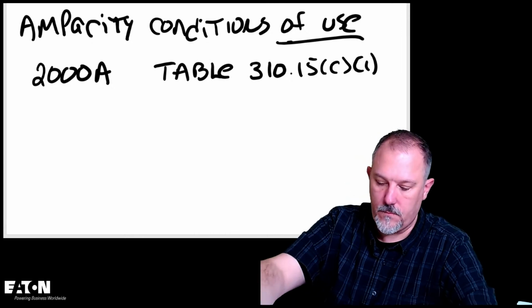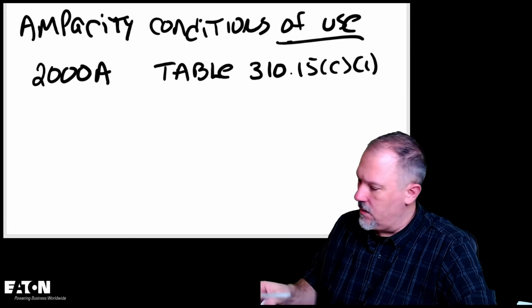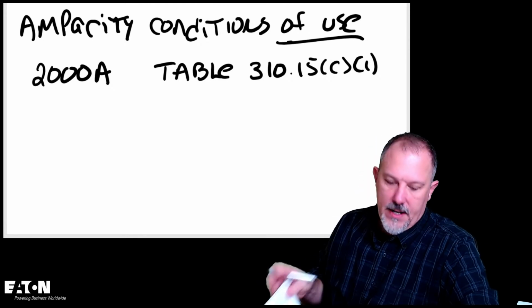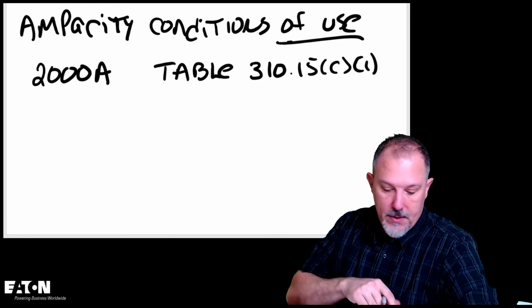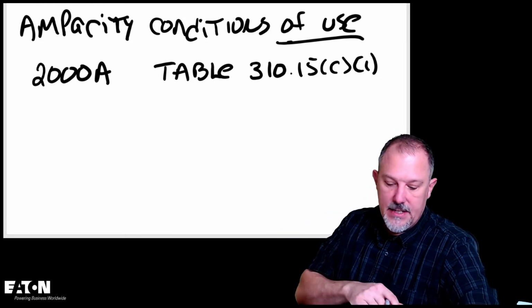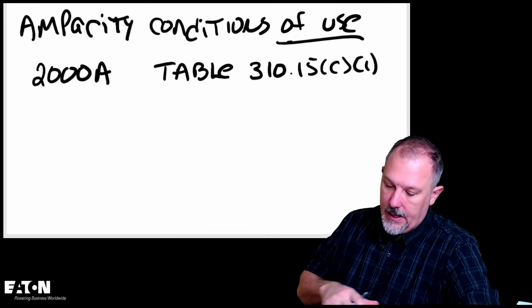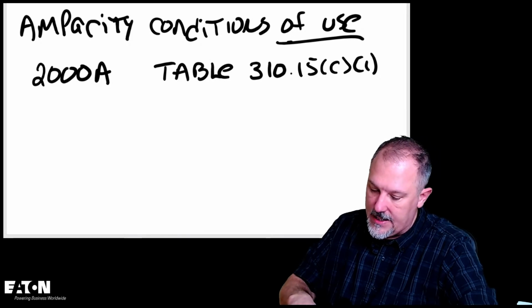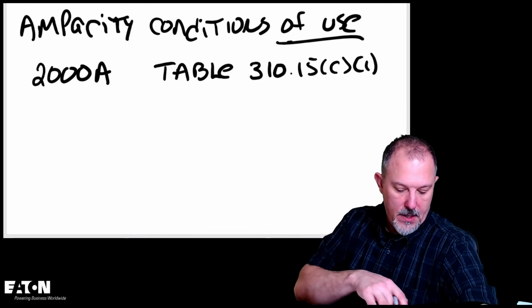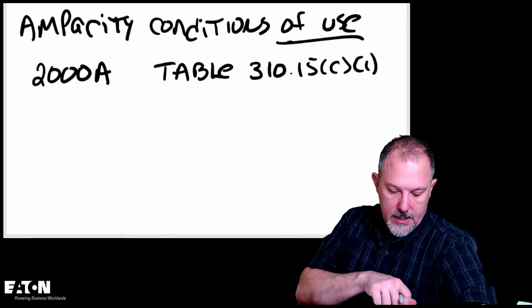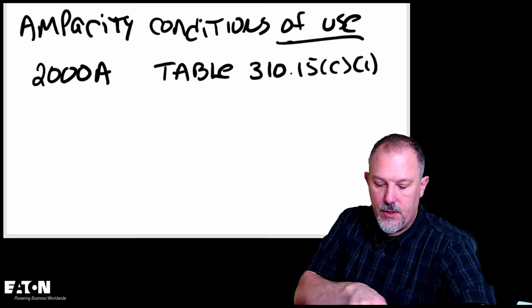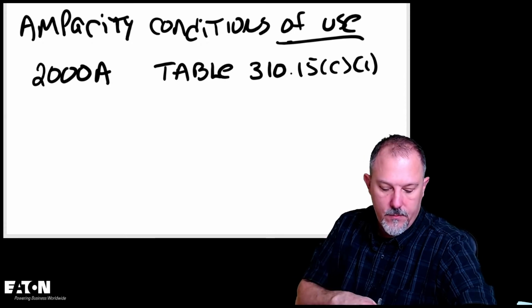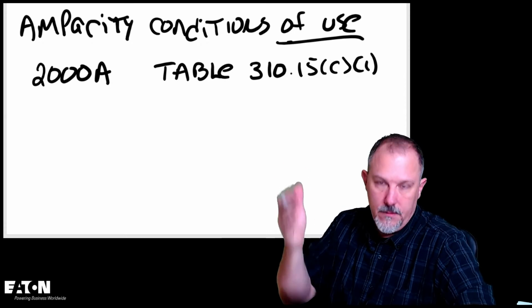Let's just take a look for everybody. So he says Annex C. Annex C is an informative annex, and basically it has the trade size, the type of conductor, the conductor size, and the different size metric conduit raceway, right?